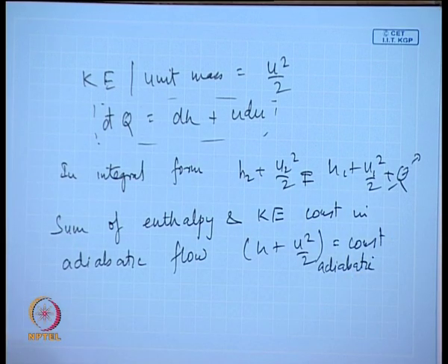From the energy balance equation we get it, you can also get it from the steady form of the second law of thermodynamics. You can use it and you can get it by knowing that Tds equals dH minus Vdp, is not it? By applying that also you can get it. Okay. So, therefore, we find that for adiabatic conditions, even if there is friction, even if there are irreversible effects, under adiabatic condition the sum of enthalpy and the kinetic energy of a fluid is constant. Agreed? So, therefore, at any particular point in a pipe, H plus U square by 2 equals constant.